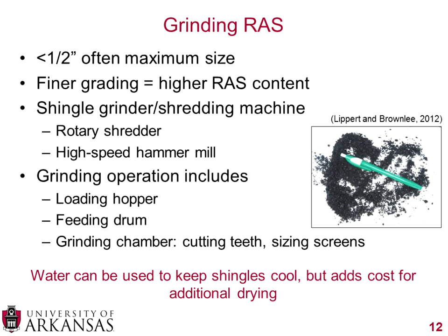One of the things I was reading about that was a potential concern was heat during the grinding process. Obviously, a lot of our work takes place in the summer. There's a lot of sunlight, a lot of heat builds up, and grinding RAS can get very, literally, sticky if you're not careful. And they say that you can use water to keep the shingles cool, but a big disadvantage of that is that you'll have additional costs for the drying on the other end, because at the end of the day, before you put the material into a drum, you do want to minimize the amount of water you have.